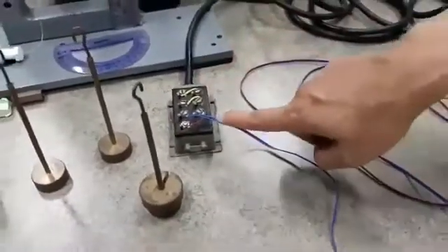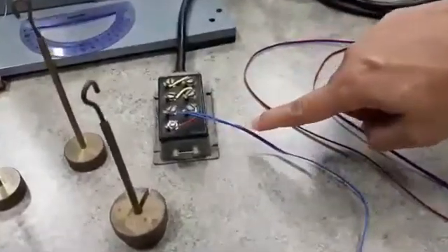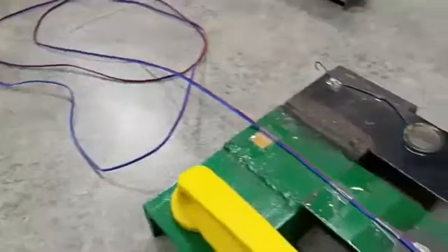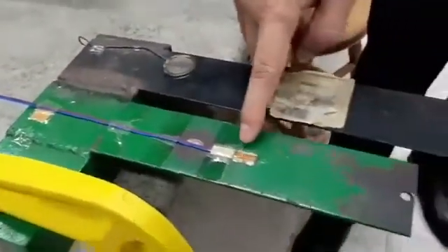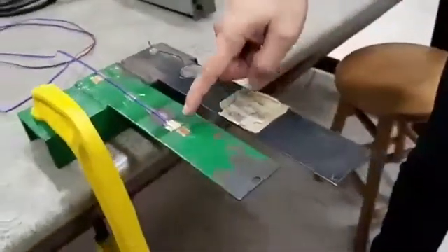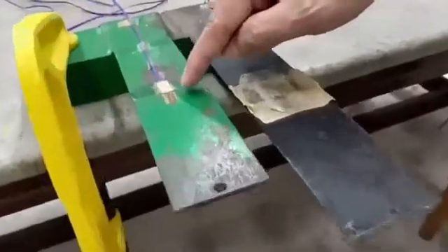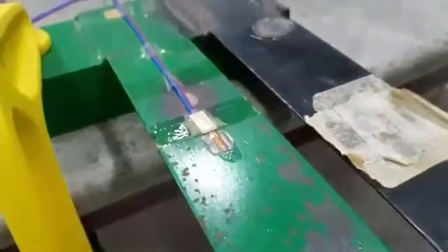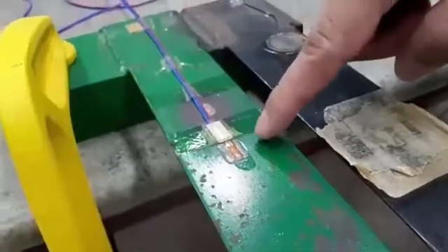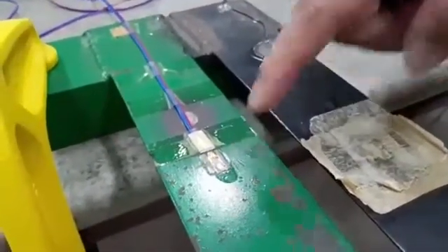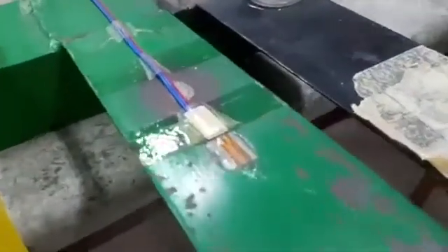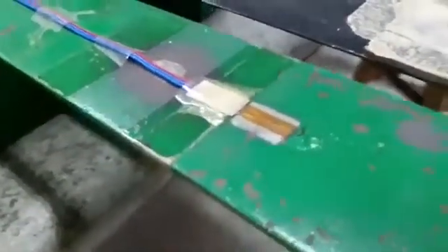And then you could see a cable, a wire here, moving to the strain gauge. See, this is the strain gauge. You could see closely, we glued it on the cantilever beam. So this is part of one resistance, which I said varies with the deformation of my cantilever beam.